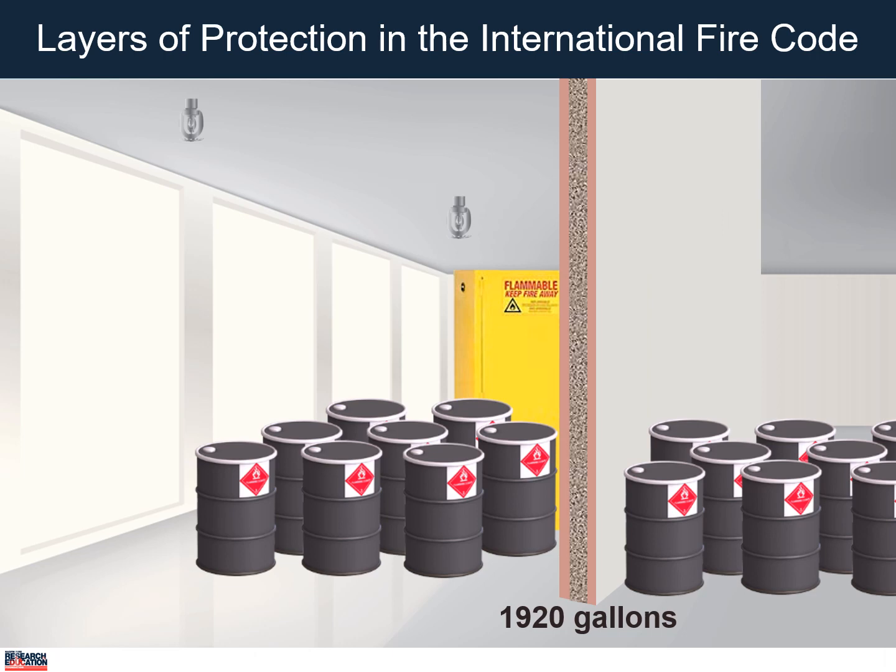separate fire compartments called control areas can be built to gain another increase. Each control area can now have up to 480 gallons, and a building is allowed up to 4 control areas for a total of 1,920 gallons of Class II liquid. We haven't changed the classification of this building, and we've gone from 120 gallons to 1,920 gallons by adding several layers of protection. Beyond 1,920 gallons, the code would require the building to be a Group H occupancy, which has even more protection requirements.